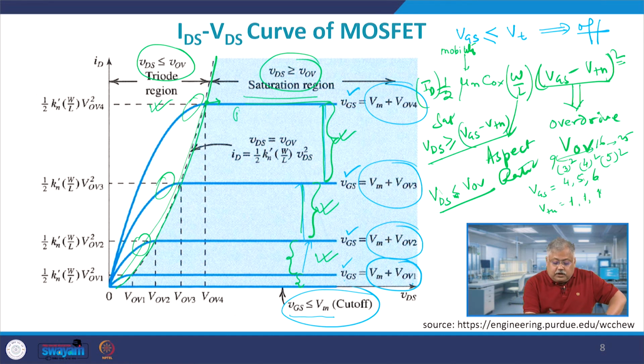If you want to find the resistance at this particular point, resistance is voltage by current. Here, the current is almost constant. So if you look at del V by del I, this will be infinity, because del I is 0, and therefore resistance will be infinity, which means that the output impedance of a MOS device in the saturation region is infinitely high, right? And in this other region, it will have a linear component in the value of your R, correct? Please keep this in mind, we will be using it later on in our discussions.